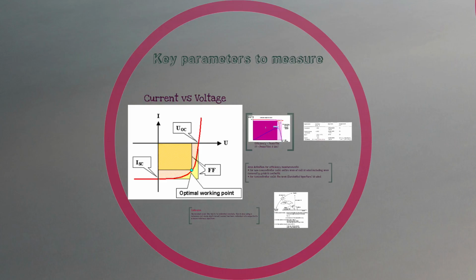What we're trying to measure first, for a solar cell, of course, is the electrical characteristics, the most important thing. It's a PN junction, as we all know. We reverse bias it, right? That means the PN junction has a negative voltage applied to it. And typically, if you look at the curve, you look at the reverse bias current under the illumination conditions.